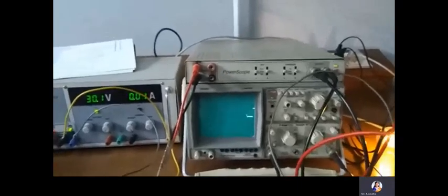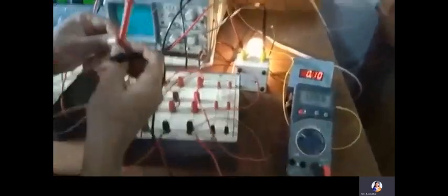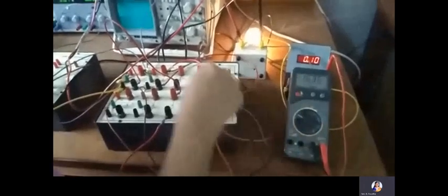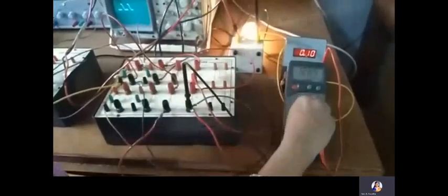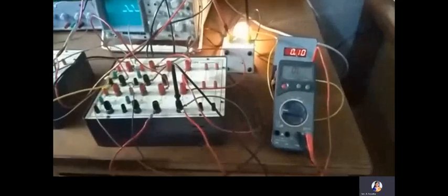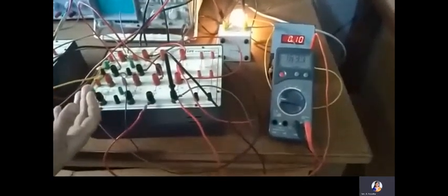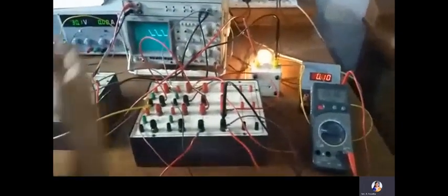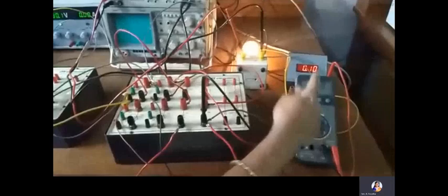Now when you observe the voltage across the load, I'm going to connect multimeter across load. One load terminal is going to the ammeter, so I'm putting it here, and the other load terminal is going here. The mode should be in DC mode because rectifier output will be DC. Rectifier converts AC to DC. Now for alpha equal to 90 degree, the output voltage is 150.2.